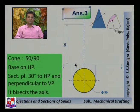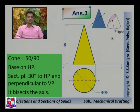So at a distance of 90 mm from this XY line, mark a point over the axis. So these 1, 2 and 3 points are there. Join these 3 points, which represents the front view of this cone. If you look from the front, it would appear as a triangle as represented over here.